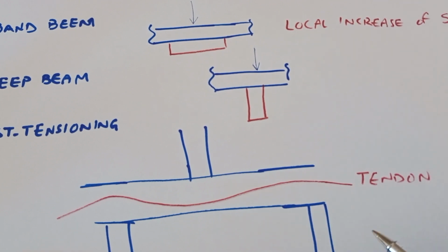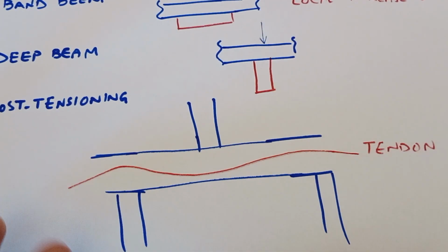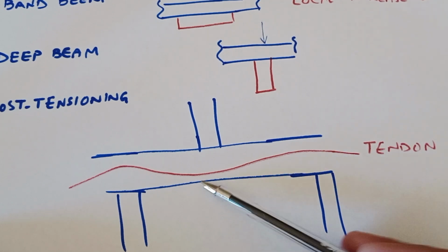But still, there are some limitations for tendon application, for example if the span is over 7 meter, that is useful. If it is under that, in general we can say that a tendon is not a good solution for deflection check.